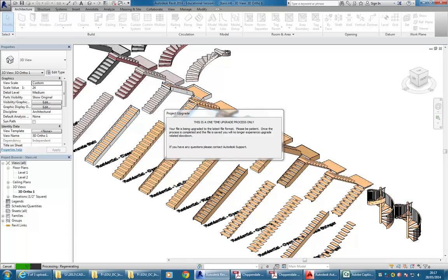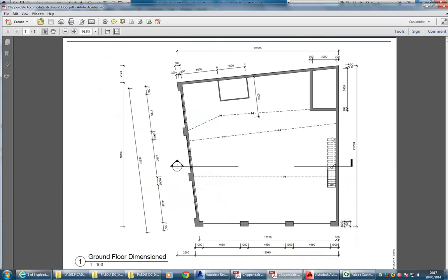And while that's doing what it needs to, just again think about what's above the stairs and also the beam. The reason the beam comes across here is so that you can get headroom from that point onwards above that stair, and that's why the landing is there as well. You wouldn't normally need to have it that way.